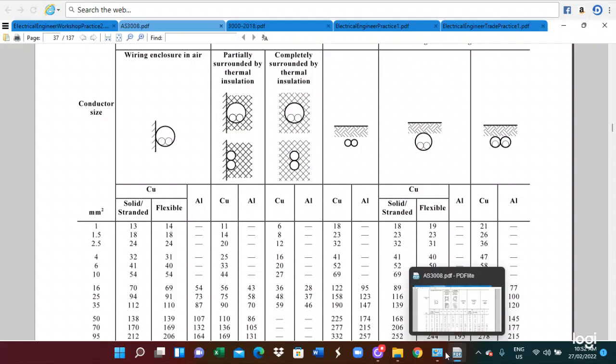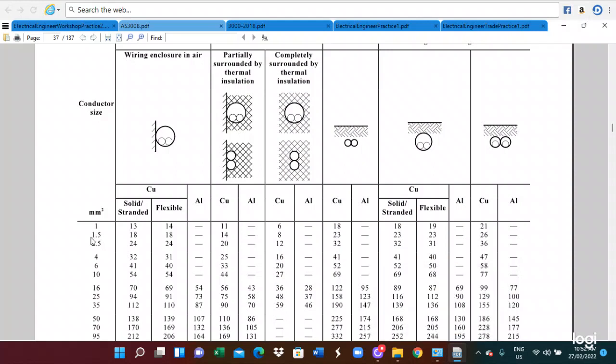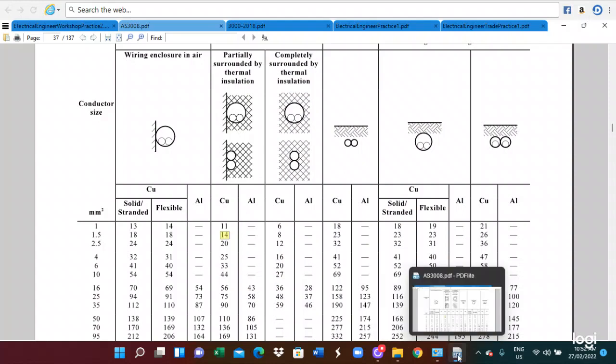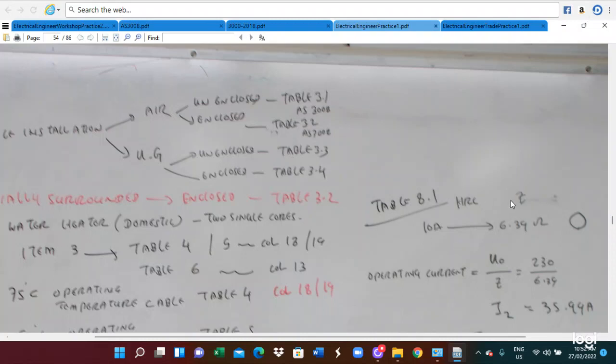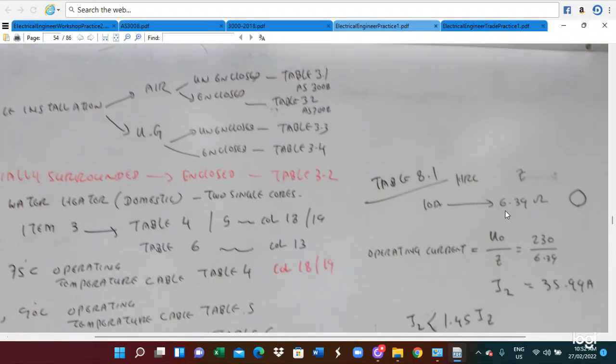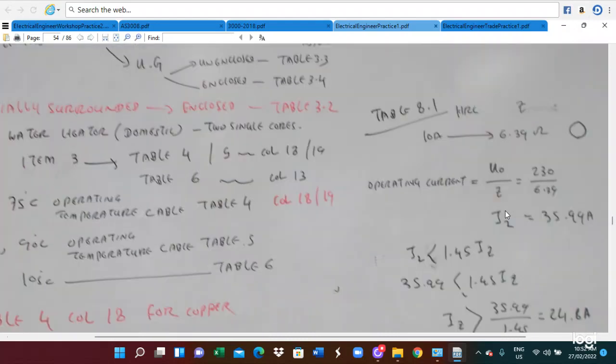From this cable we are using, if you select 1.5 millimeter square, firstly we start from selecting the cable. The minimum cable size is at least 1.5 millimeter square. In this case, if you select copper, the cable rating current is 40 ampere. So then here we can now get the fuse rating; the operating maximum demand current is 9.56 ampere.